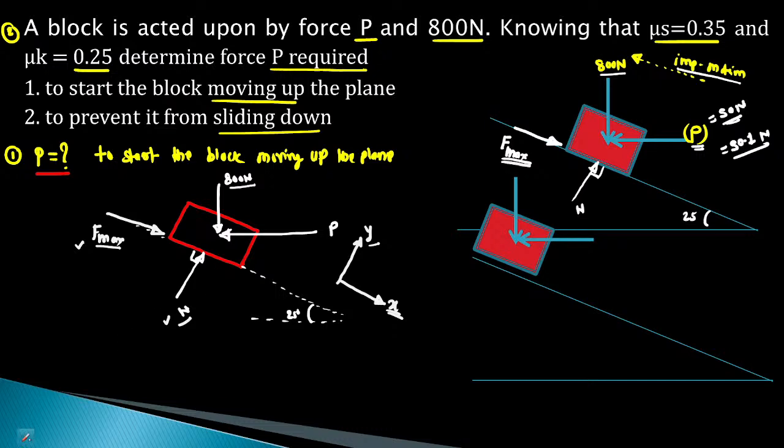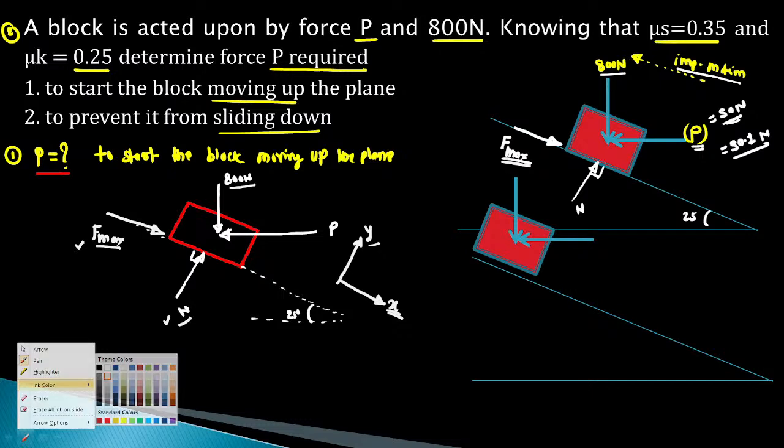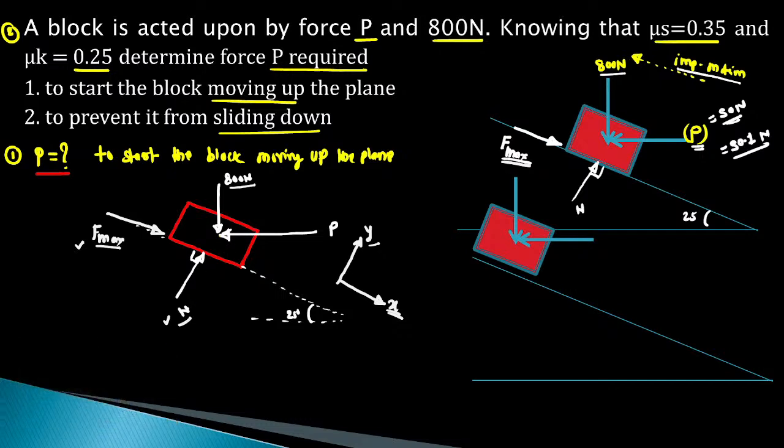So, for that you can resolve the force at this point or at any other point along this line of action. So, I will just consider the point here and then draw the vector parallel to y axis, draw the vector parallel to x axis. Now, observe the direction of this arrow. Okay. So, component must be in the same direction. So, this is the direction of x component and this is the direction of y component.